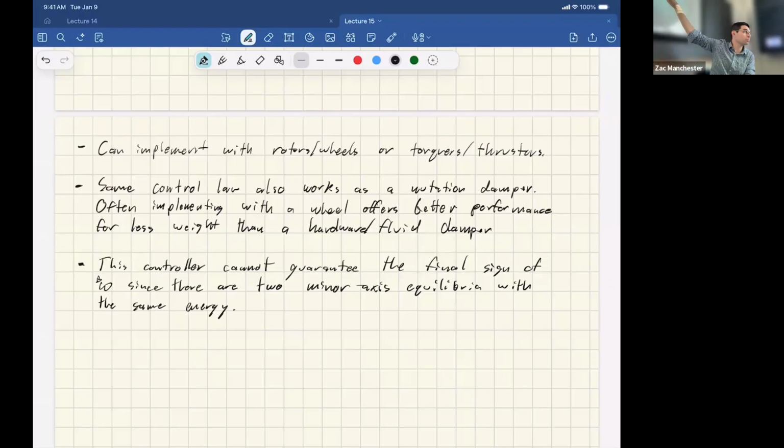And this is the momentum sphere picture, right? So these are the equilibria. We've looked at this kind of thing. This is the unstable one, and these are the separatrices. And then these are the stable ones. This is like major axis, minor axis. And then there are north and south poles that are the same, right? These are the gyrostat dynamics that we just wrote down, and here I'm rewriting them in terms of angular momentum instead of omega for convenience. This is cartoon Lyapunov stability. The idea is we have a Lyapunov function V that's a bowl.